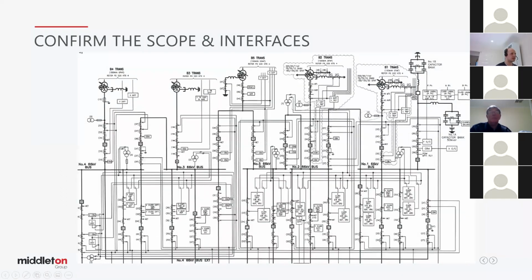So from the single line diagram, we jump into a lot more detail. So we've now found our protection single line diagram. This is on the 66 kV side, and that really details our current transformers and where they sit in terms of the transformer. They may be internal to the bushings of the transformer. They may be external in the form of neutral CTs, which may be procured separately from the transformer, but may be required to be specified, and they might be for restricted earth fault protection, which we can see here, going into the transformer differential box, which is really our relay.